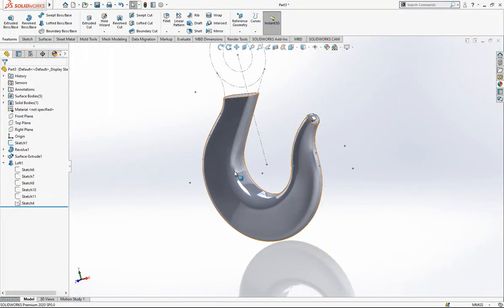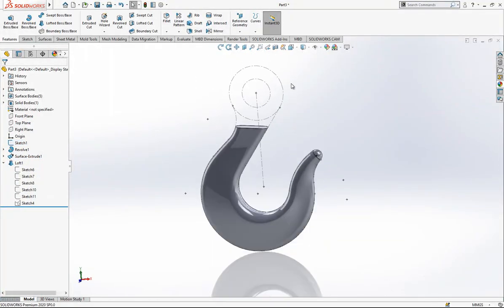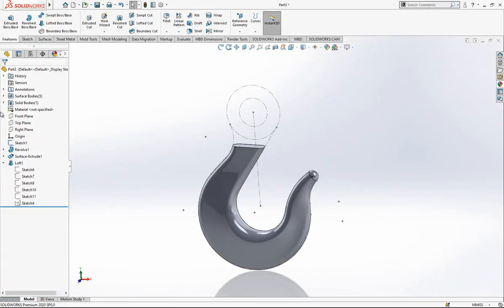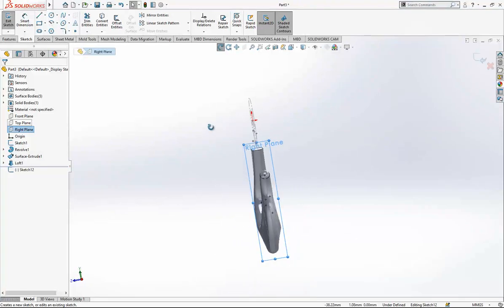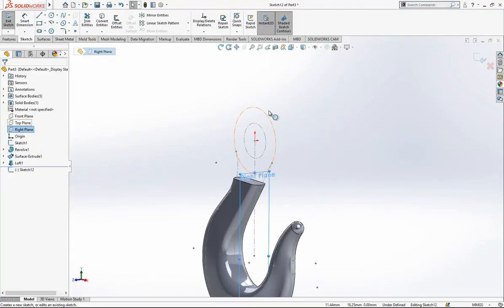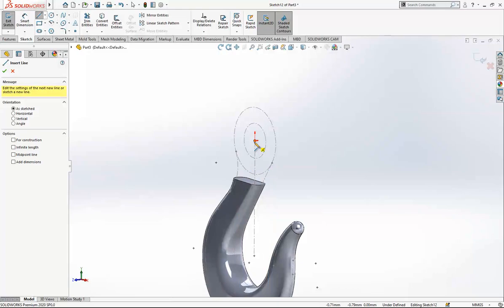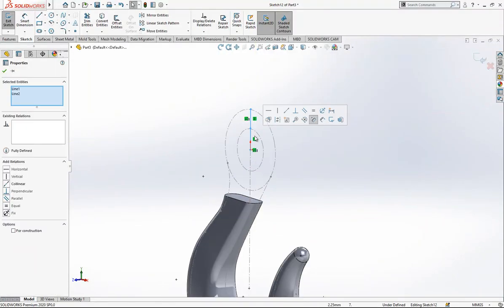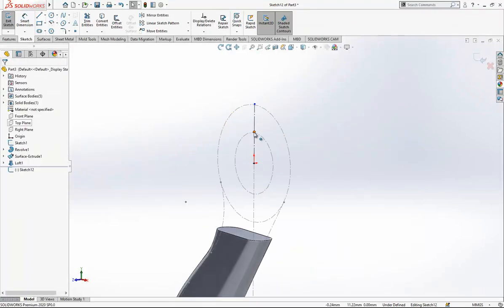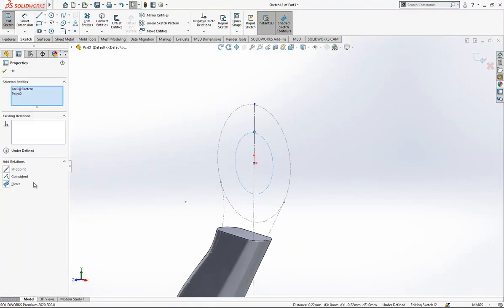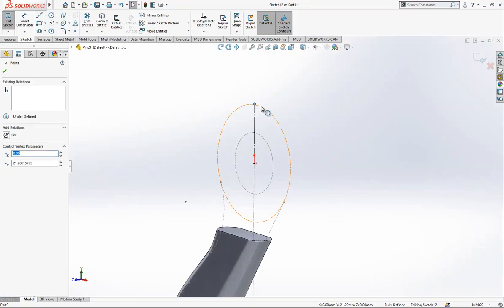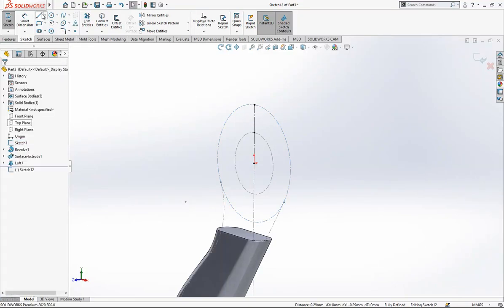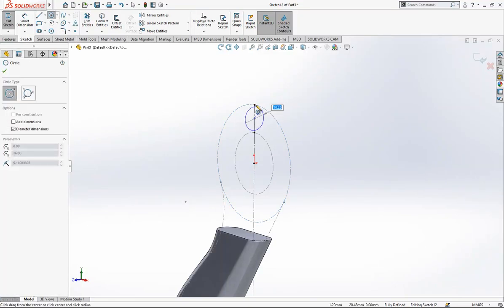And I can show you again our first frame. And now on the white plane, I will create a sketch, in this direction. From here to here, one line, and from here to here, one more line. Both of them will be construction geometry. And while control clicked, I am giving a pairs relationship in order to find the middle.